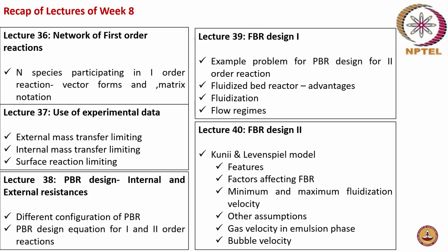Lecture 40 was also on fluidized bed reactor design, where the Cooney and Levenspiel model was discussed. The features of the model, the factors affecting a fluid bed reactor design. So, for example, the mass transfer rate, the bubble residence time, and the rate of reaction are the factors affecting a fluidized bed reactor.